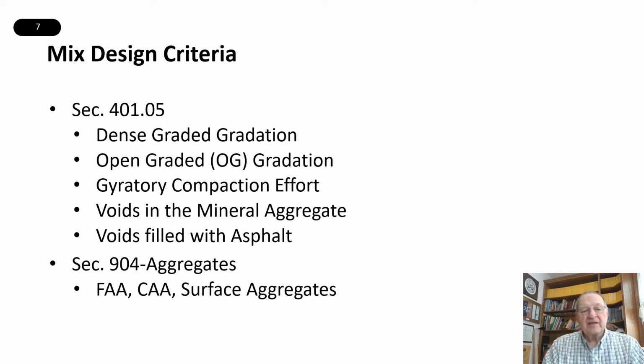The aggregates are specified in section 904, and the requirements for fine aggregate angularity, or you can think of that as crushing in the fine aggregate, coarse aggregate angularity, which is crushing in the coarse aggregate, and then surface aggregates, meaning friction type aggregates or aggregates that are wear resistant for high traffic conditions such that they will maintain their friction values for wet weather stopping conditions.